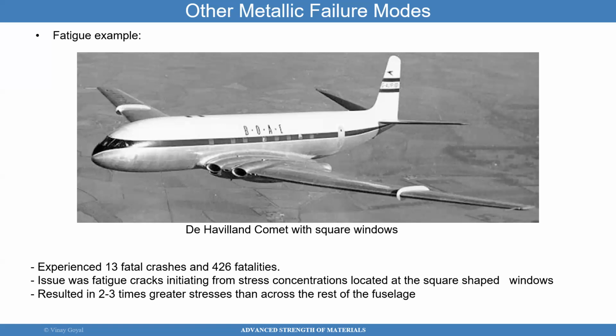So now I land again. I went from 0 psi to 10 psi, and then I dropped to 0. I repeat that 6 times, and I fly that same aircraft every day, say, right? So I'm putting a lot of stress, fatigue, life reduction into that aircraft. The life is getting dented over and over.